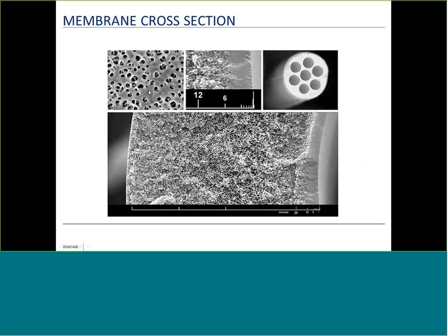And the system cleans itself by opening a drain valve and flushing rapidly water that's been already processed from a tank, stored, and flushing backwards. It can be done with raw water, but it's more effective with filtered water to flush that debris off the skin of the separation core of the UF membrane.